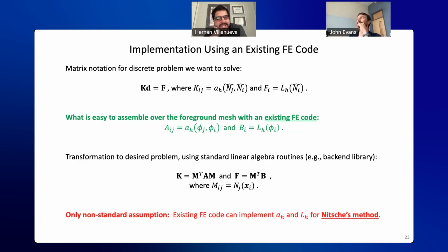Okay. And your level set field is still linear, or have you guys done any quadratic when you represent those shapes? Yeah, so we have the capability for representing shapes other than linear. Nils Wunsch in particular was starting to investigate that. And one big reason we were looking at that was leveraging higher order rules that Xiang had developed that read level set descriptions directly without any meshing. So that inspired us to look at that, but that work is unfinished at this point.